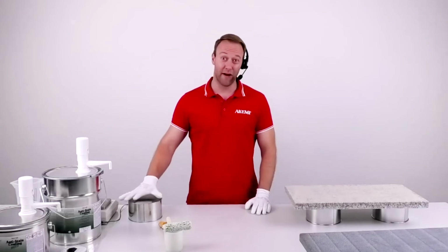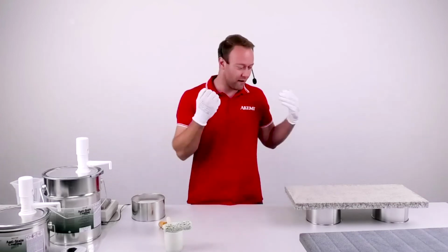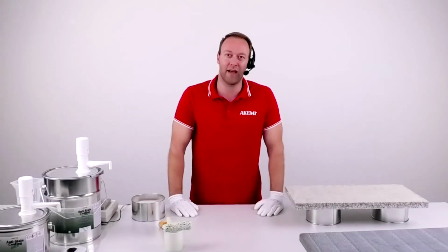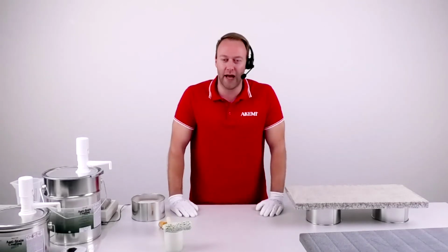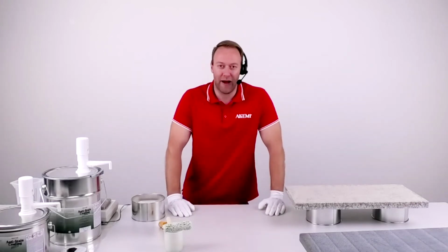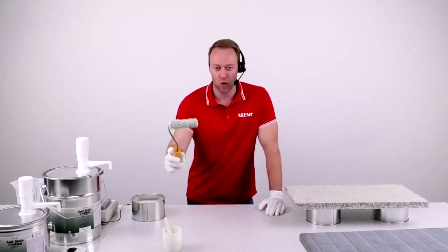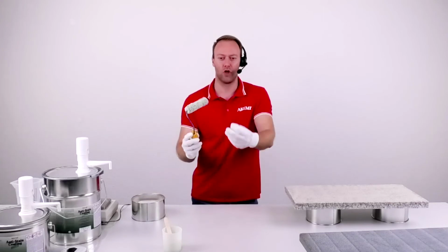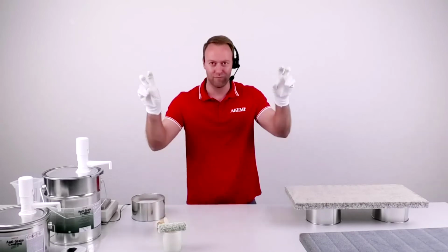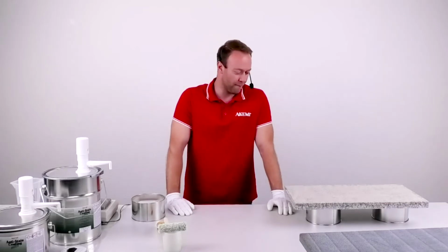Better do it in the factory when it's like 35, 40 degrees ambient temperature, and not when there's direct sunlight, of course. It will just reduce the application and curing time. So if you can adapt to that, lucky you. The product doesn't care. But it's better for the workers to keep it workable, because if it's too hot, your roller starts to cure and becomes sticky. So better to keep a moderate temperature, 35, 40 degrees, usually should not be a problem.